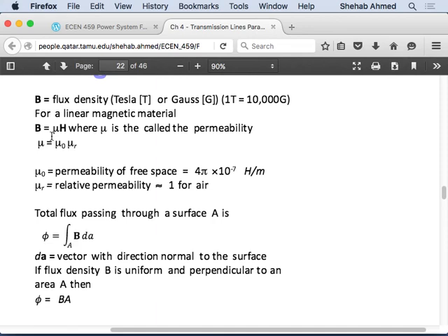There will be flux linking certain portions of the conductor due to the magnetic field inside the conductor, and once you go outside the conductor, the magnetic field is linking the conductor itself, regardless of how far you go. So there will be two components of magnetic field that we will have to calculate, internal and external to the conductor.